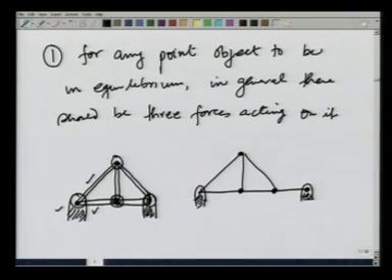However, the moment I do that, this joint will not be in equilibrium, because this is acted upon only by 2 forces, one by this fixed joint and the other by this rod. So, I have to provide one more member to bring this point into equilibrium. The moment I do that, I have one free end of this member here, which also has to be brought into equilibrium. I could provide one rod this way and one rod this way, and this entire structure would be capable of remaining in equilibrium. This is a truss, a plain truss. So is this.